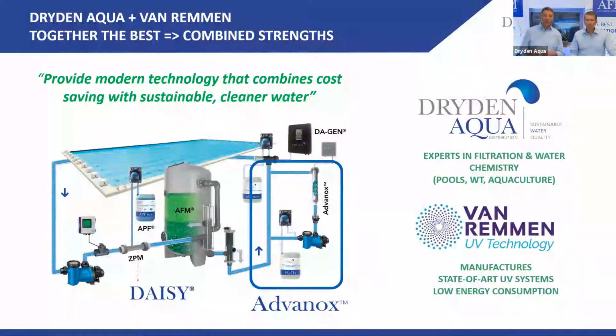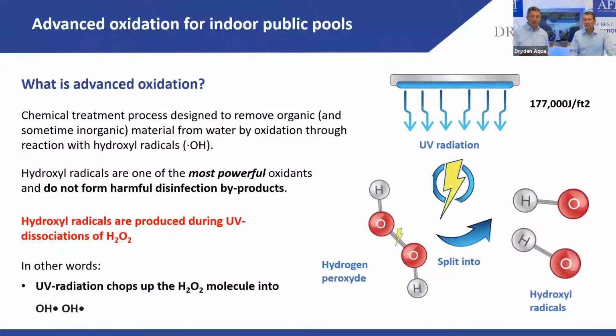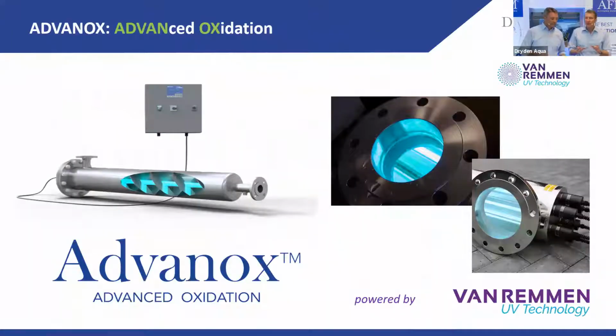And Howard said, okay, why don't we bring advanced oxidation in here and we just treat a small side stream, a very small side stream. Okay, so why this? Because this really is a big advantage that we only need to treat the water in a very small side stream, and the side stream is about 3% of the water volume. But really, the main reason is because of the organics, the organic chloramines.